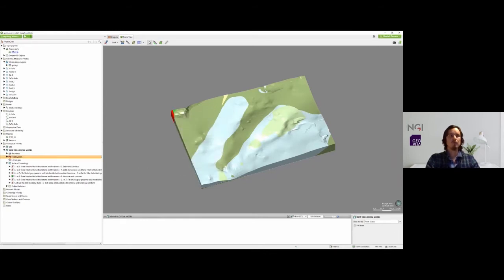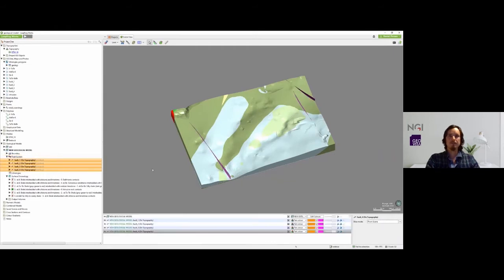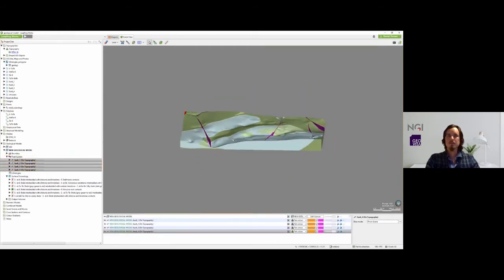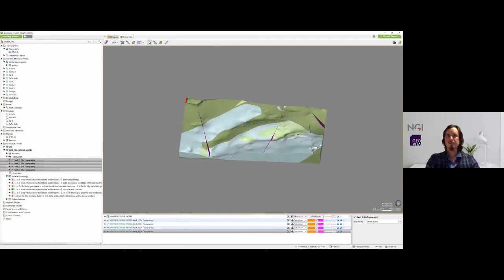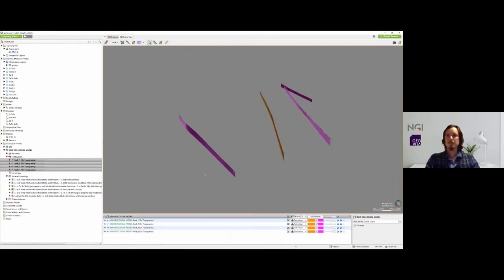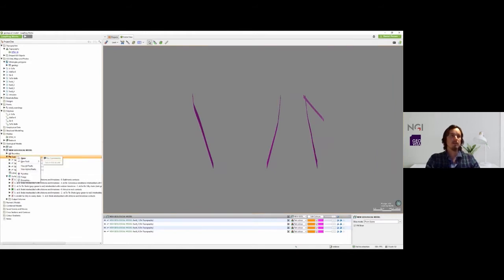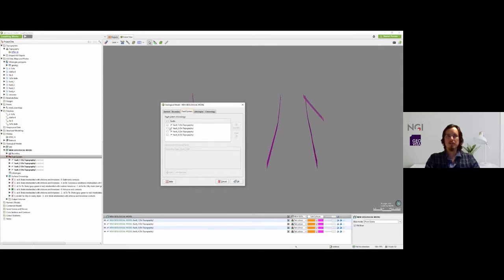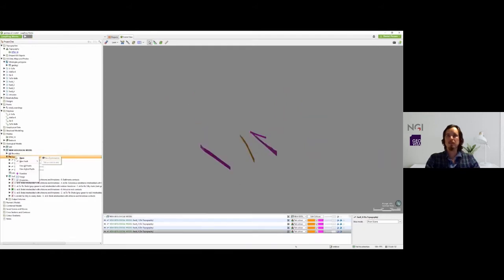Okay, and we can view the surfaces created for the faults. Here we have the surfaces. And up in the right corner, we gotta terminate one of the faults against the other one, and that we can do with opening the fault systems and hit on the fault that we want to terminate and add it. It should terminate against fault 1 on the southwest side, and then okay.